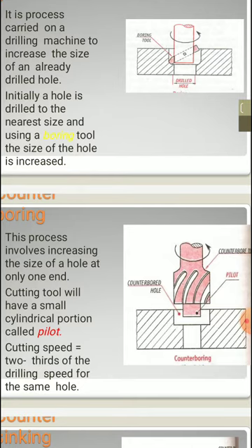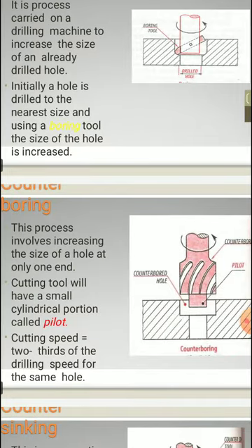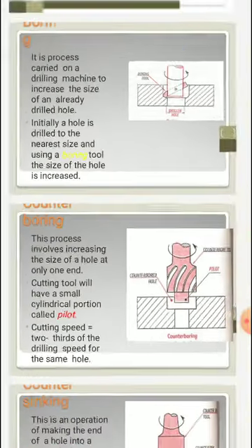So to increase the size of the hole only at one end, this kind of counter boring operation is carried out, okay, and the tool is called a counterbore tool. And the cutting tool will have a small cylindrical portion which is called a pilot.